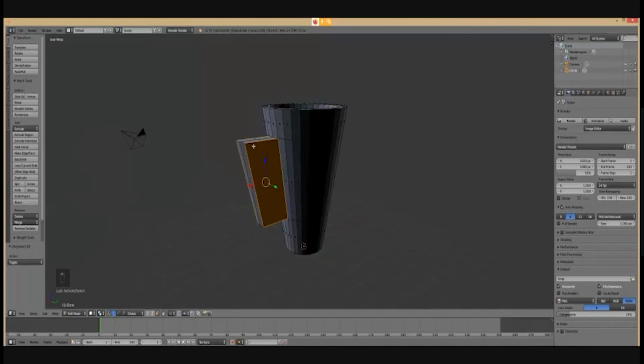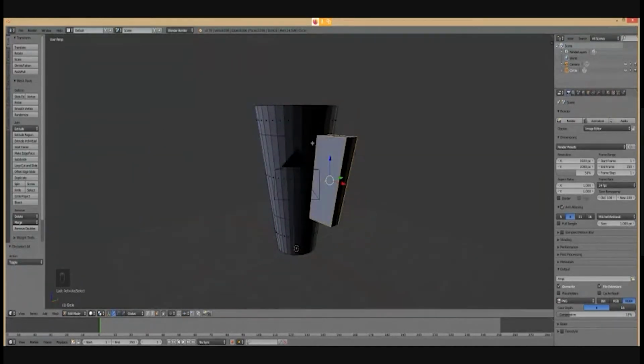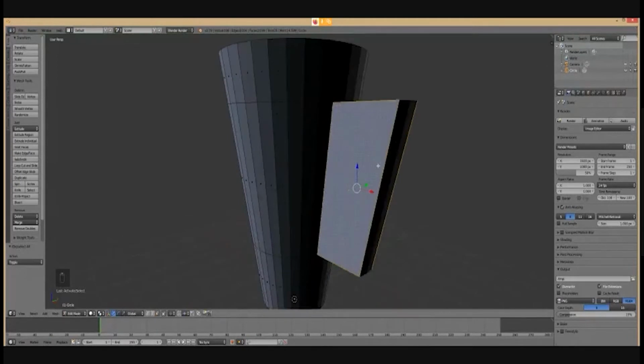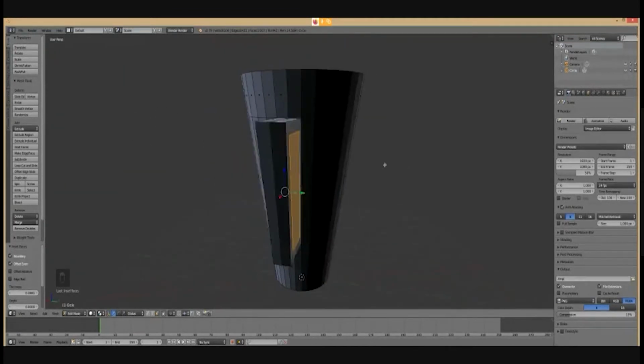So I have selected two faces, right? Once I have selected two faces, I will use the inset shortcut, which I talked about in the beginning. So I press the keyboard shortcut I, right? And I can basically move it in like this, right? So let's say this much is fine, right? So inset has happened on both the faces.